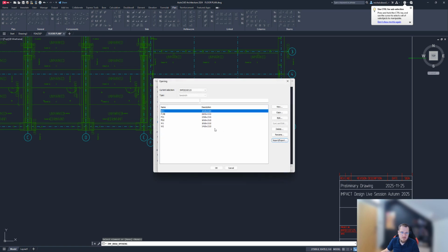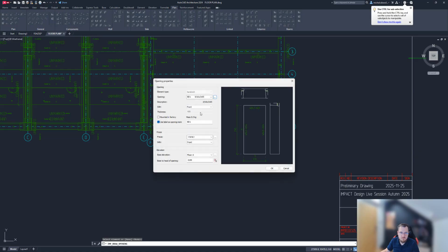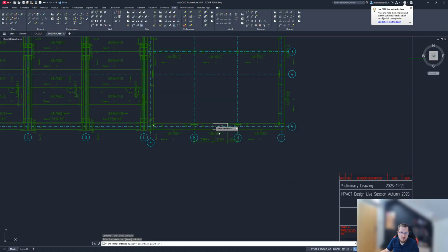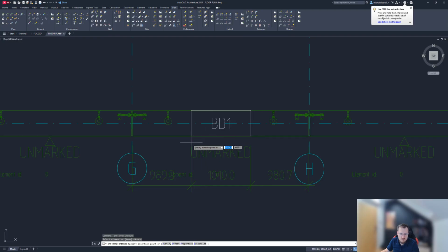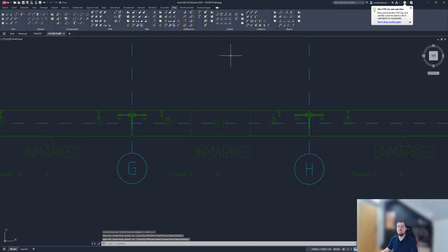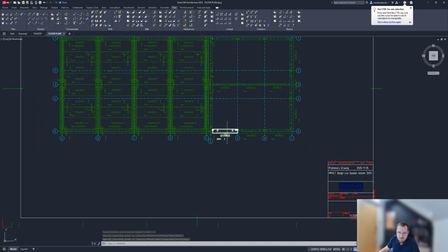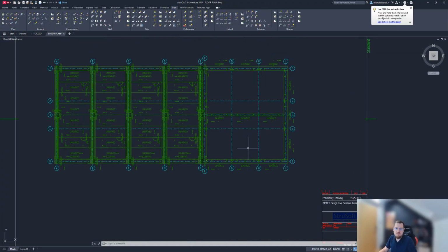Okay, this one actually we have to import. Let's use that. That's the balcony door, and for example we can specify the justify center, and for example midspan of this door, of this wall, we can do that. And with that, you will see that, for example, for this particular wall, the reinforcement has been added automatically once we open up the drawing.